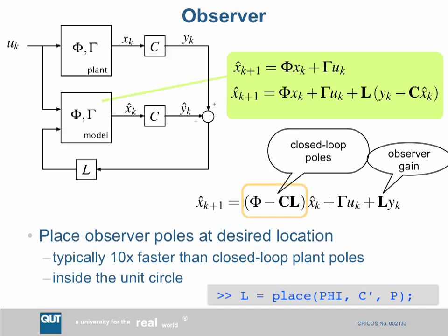This is how you connect the estimator to the plant. This is where the state feedback gain is up there. So we have the estimated state. We have the desired state of our plant, which I called X star. Take the difference of those, multiply it by the state feedback matrix, and push that into the system. And there you go. That's how you do state space design, controller design, and estimator design for discrete time systems.